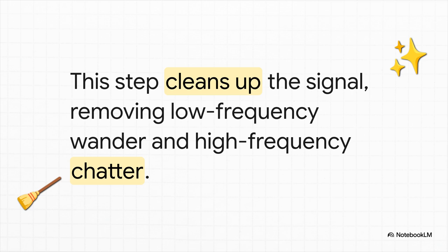First up, we hit it with a bandpass filter. Think of this like a bouncer at a club. It's designed to only let frequencies in a very specific range, right around where the QRS complex lives, get through. Everything else gets rejected. And just like that, you can see a whole bunch of that low and high frequency noise is gone. It's already so much cleaner.